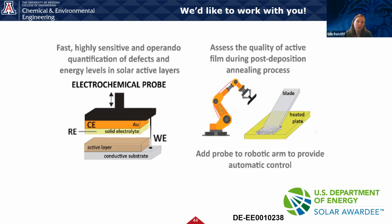The other thing we're interested in, like I said, is degradation. Can we track how defects are evolving? We accelerated it just because we don't want to wait a long time, and we didn't encapsulate. But you could imagine that if we could encapsulate the device and monitor the power conversion efficiency for thousands of hours, and then open up the device and look at it, we could start to see what defects have formed.